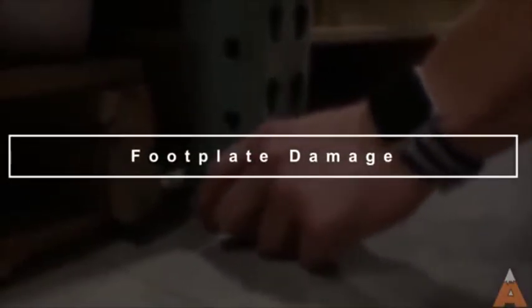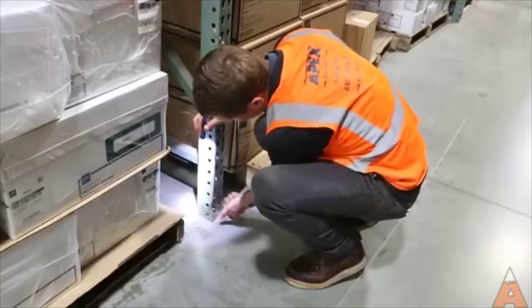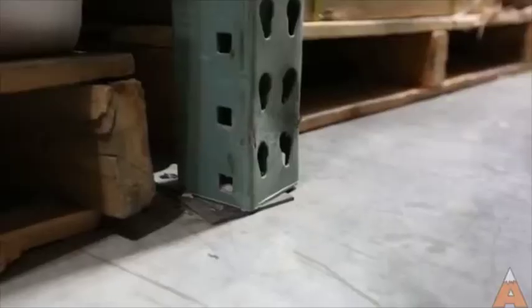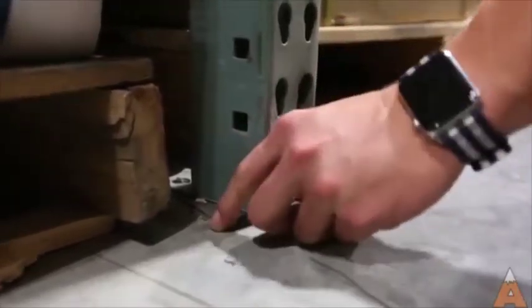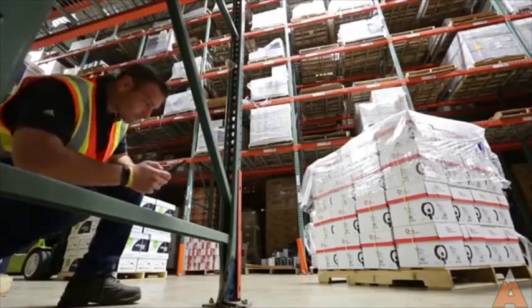The footplate connects the rack system to the floor. If it is missing or compromised, the system may not be properly secured to the ground. Check for rips or tears, and if the footplate is twisted by more than a ½ inch, you need to record it as damaged. Also, note any shims to ensure they are not sliding out or improperly installed.